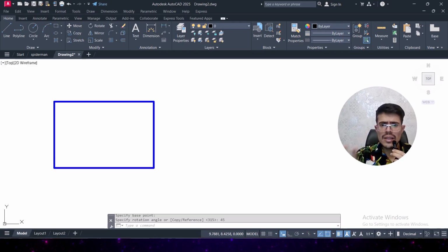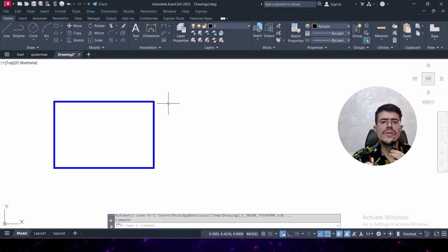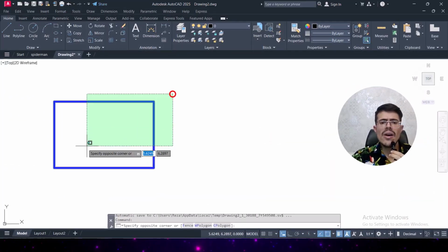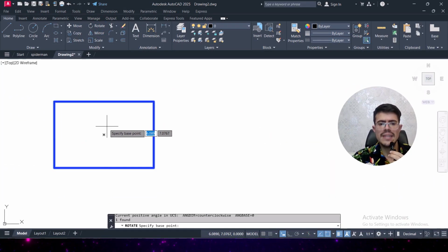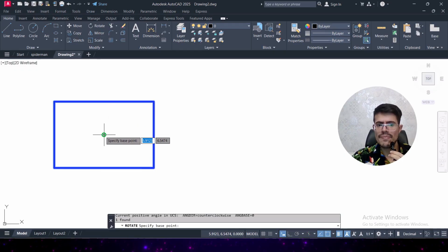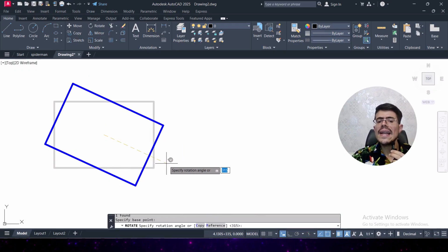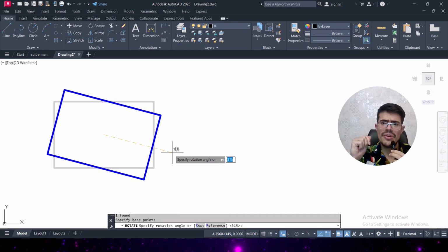So that was all the information about the basics, but let's go into some more advanced cases. Now if I select my object and select the rotate command, and select this point, as you saw previously, when I use rotate, my first object is removed and I have just one object. But maybe you need to keep your object and make a duplicate rotated form of it.